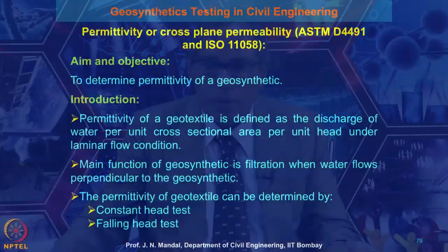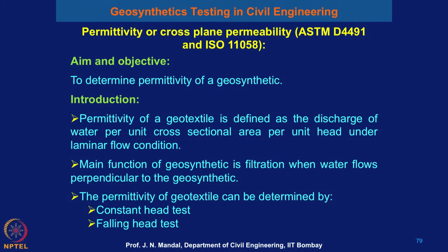So I will proceed one by one on how you will perform all these tests. First is the permittivity, or cross-plane permeability, and this test is performed as per ASTM D4491 and ISO 11058. The main objective of this test is to determine the permittivity of a geosynthetic material.